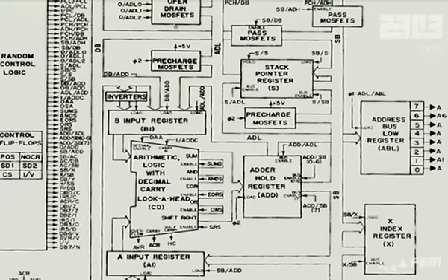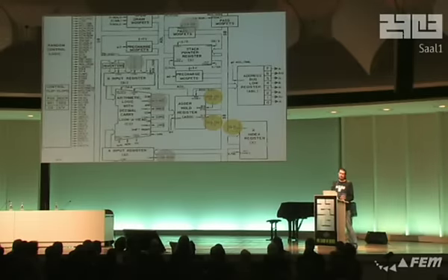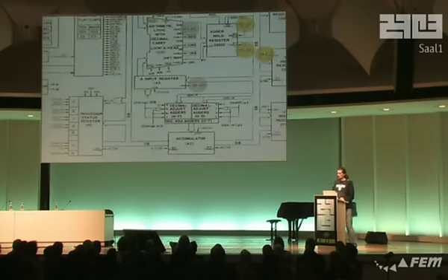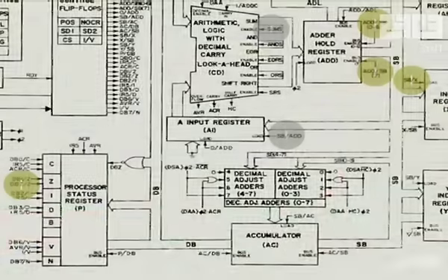Then in the second cycle, we have to get the add or hold register output, put it onto the S bus with these two control lines, and we store it into X in there. There are a few more bogus junk control lines there to keep the ALU occupied, which are a side effect of the way everything is encoded and the way don't care works. So this doesn't have any influence on what's actually going on. But there are two more lines that are asserted: the one that sets the 0 flag, and the other one that sets the negative flag from the output.